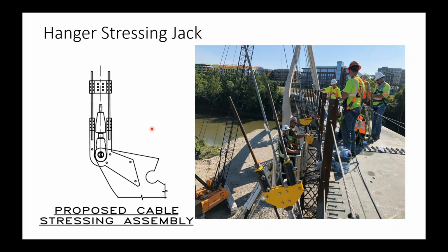And this is an element, you know, during the design phase, we don't typically like to get into construction equipment or dictate means and methods to the contractor. But in certain cases, you just have to do it. You've got to think about constructability and access when you're designing. So we had put in our concept for a stressing device on the hangers, and the cable supplier, who actually did the installing and stressing, came up with a very similar looking device.